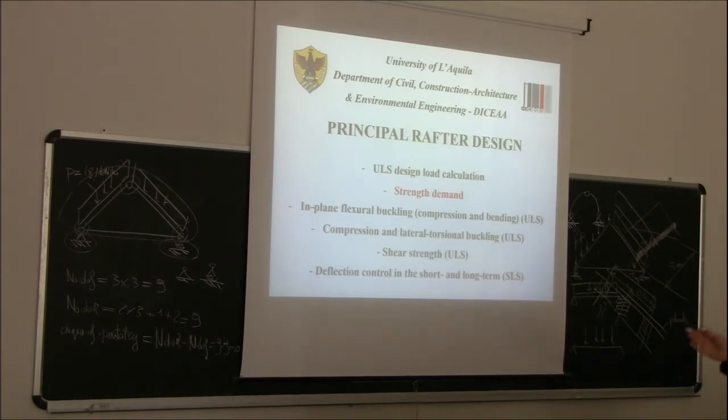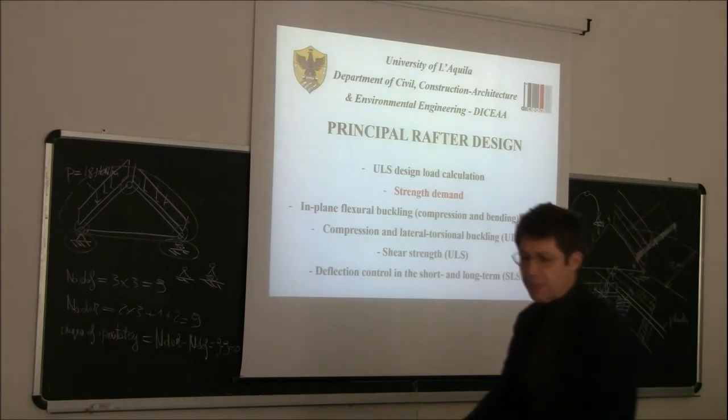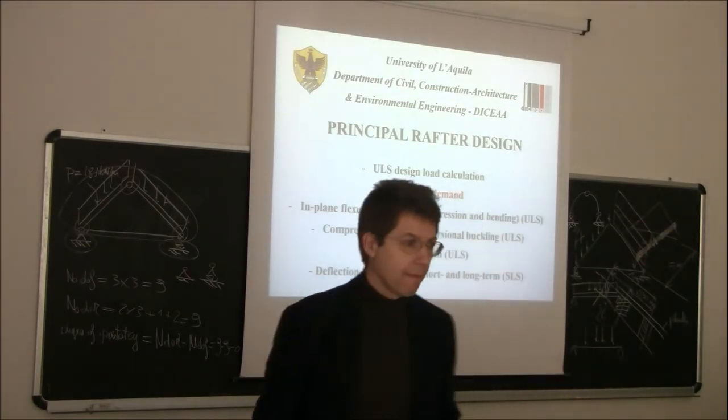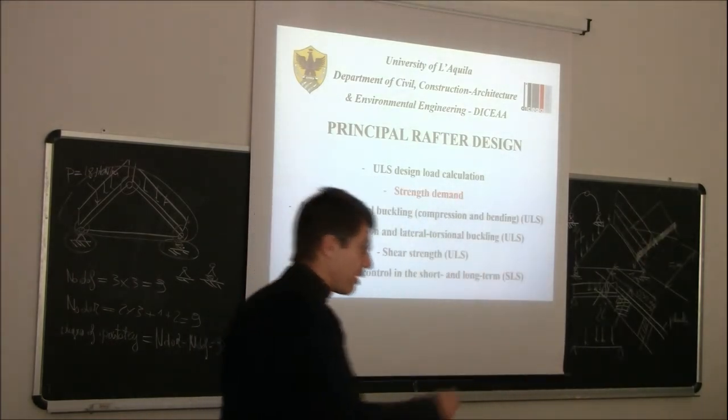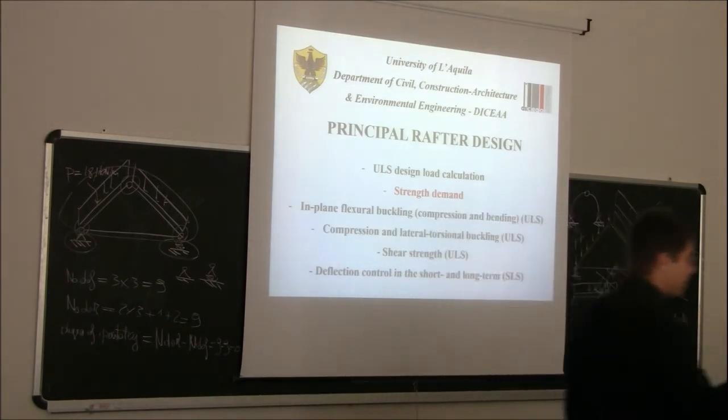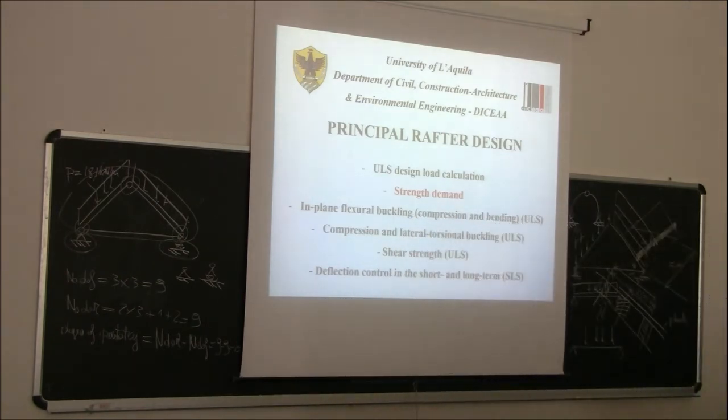Okay, so strictly speaking, this is not a truss system. If the loads were applied to the nodes, you knew that, as a property of the truss system, what kind of forces can you expect in the beams? Only axial force, either tension or compression.